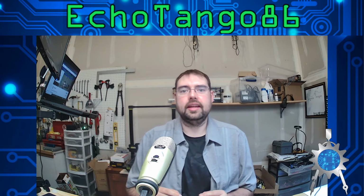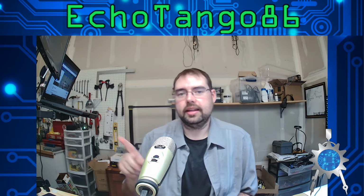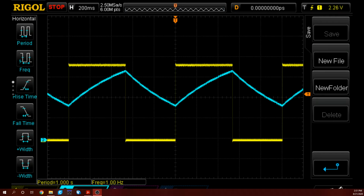Now you probably heard me say we want to know how fast it can go in hertz or period. Let me give you a little diagram of what we're looking at here. So here's an oscilloscope, and this is taken off of my oscilloscope on the clock that I had built, and it shows you and calculates your frequency and period. Let me hide my face real quick. Whoop. So right here you see period is 1 second, frequency is 1 hertz. Those are correlated to each other. Hertz is 1 over the time, and that'll calculate your hertz there. So 1 over 1 is 1 hertz.